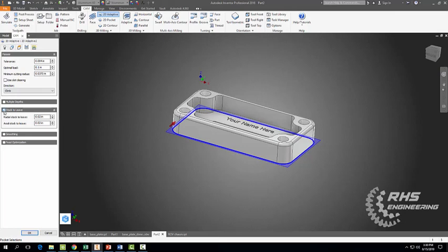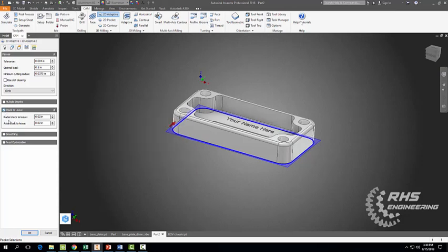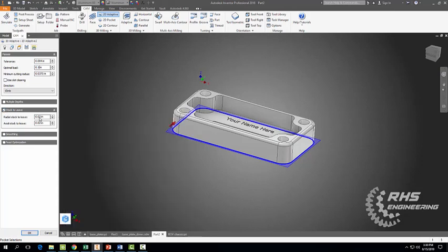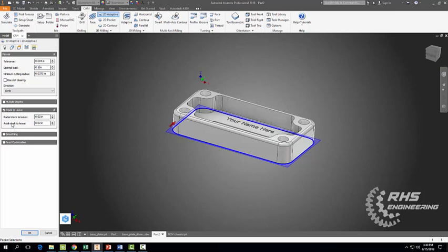And this is a roughing operation. So the whole goal of 2D adaptive is just to remove lots of material efficiently and rapidly, but leave a little bit of stock behind, okay? And in this case, we're going to check stock to leave, okay? And we're going to leave 0.02, okay, radial and both axial stock, okay?